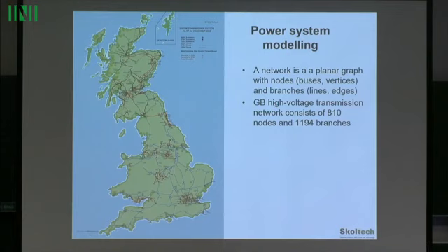And again, there were questions over lunch. Why, for example, is frequency 50 Hertz? Why are there 3 phases, not 4 phases? This is a kind of compromise engineering judgment. I was talking about those 3 phases, that you can remove the return wire. It could be 4 phases, but then it would be more complicated arrangements. You can do the same thing with 2 phases, but then the line-to-line voltage will be much higher. Why is it 50 Hertz?